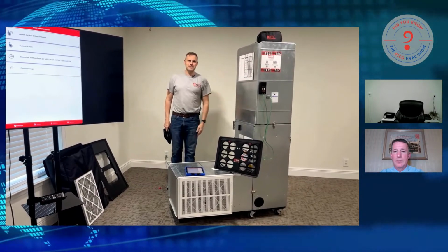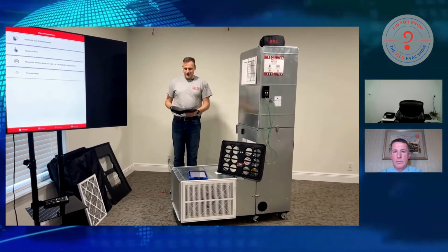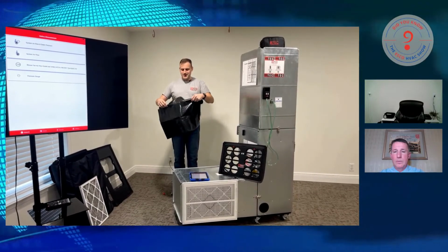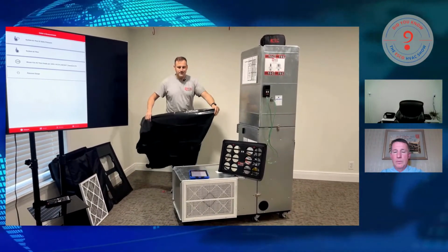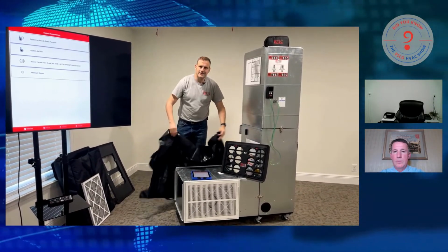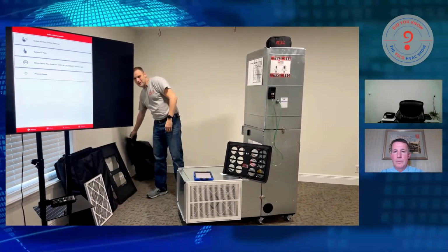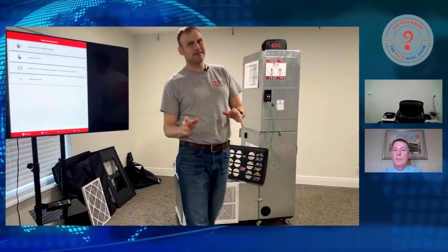Every now and then I'll go jump in the truck with a guy to go deploy the tool, keep my feet wet, right? So I took a large contractor garbage bag when I have a double multiple return. And when the fan's running, I'll lay it up against the return at the ceiling and let it suck it tight. That has worked well for me for a quick way to blank off the additional return. But we're going to get to that.